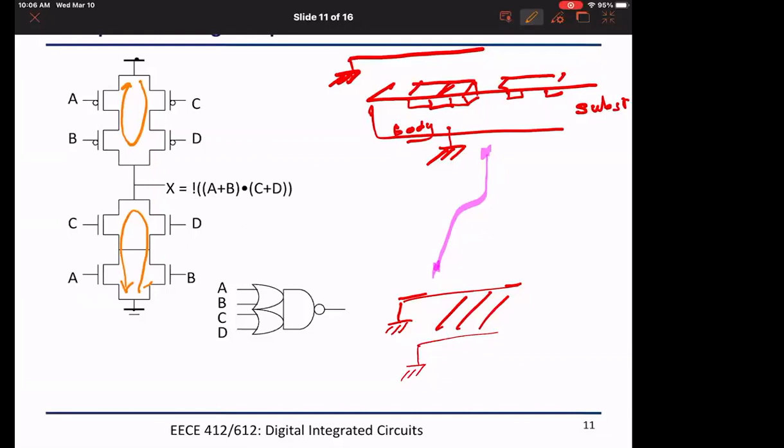Of course, if the structure of the gates is more complex, then it will become more like trial and error, unless we have an algorithm that can go over all the possible Euler paths, meaning we start working with graph algorithms, then I can find the optimal one based on my specific criteria. I have to know what my criteria are. Okay.